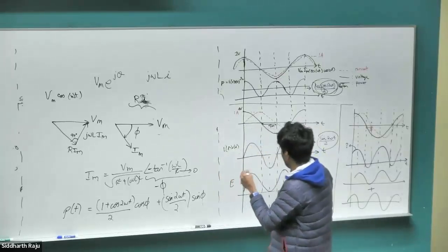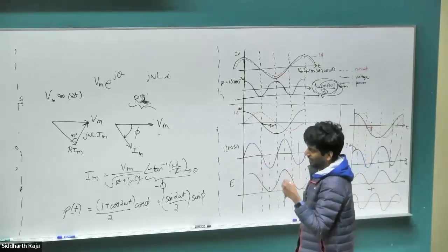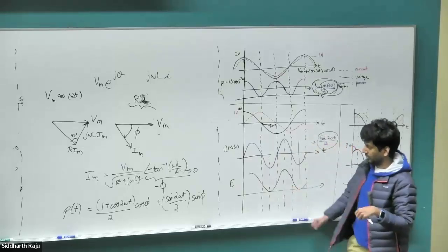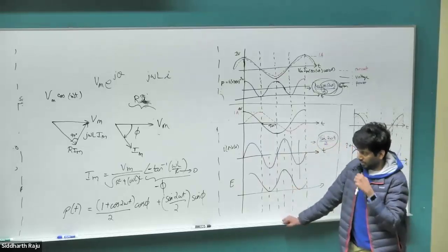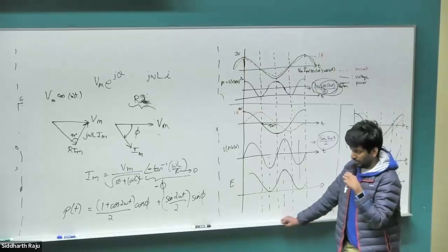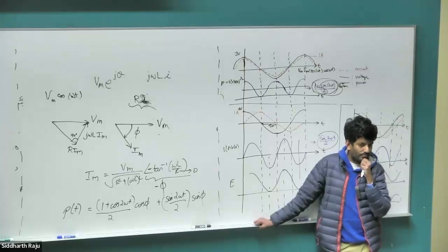While in the previous case, if you just had pure unity power factor, you wouldn't have had that additional current carrying the reactive power. So when you want to reduce the current, because you end up with a lot of losses, there is another big problem. It's not just the I square R losses, which is not significantly large compared to the load consumption. There is another bigger problem.